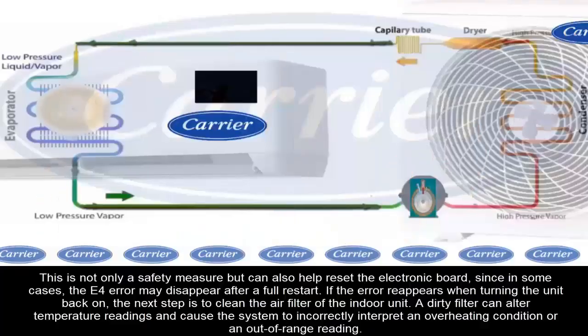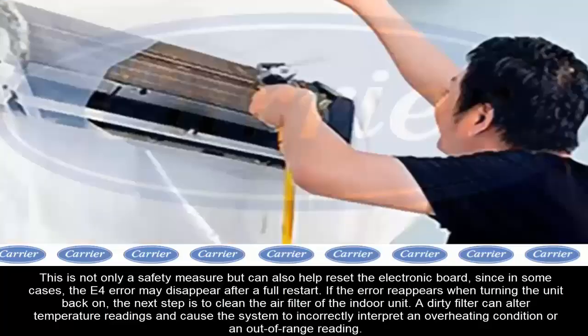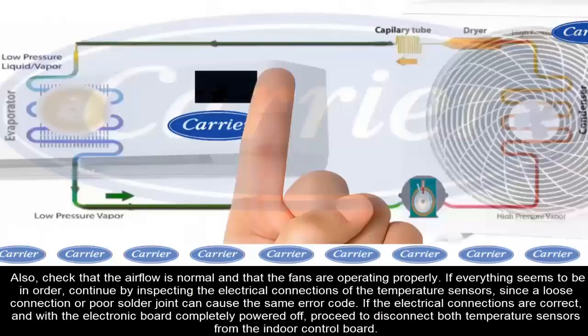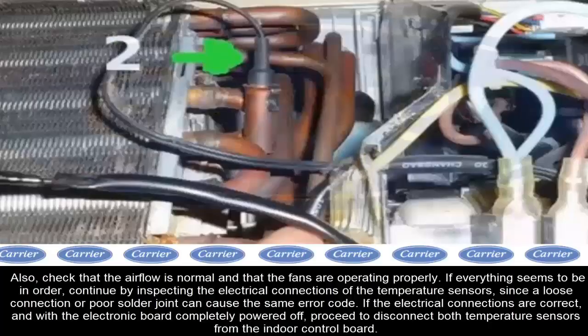If the error reappears when the system is turned on, the next step is to clean the air filter of the indoor unit. A dirty filter can alter temperature readings and cause the system to falsely interpret an overheating or out-of-range condition. Also, check that the airflow is normal and that the fans are working correctly. If everything seems to be in order, continue checking the electrical connections of the temperature sensors, since a loose contact or weak solder joint can generate the same error code.